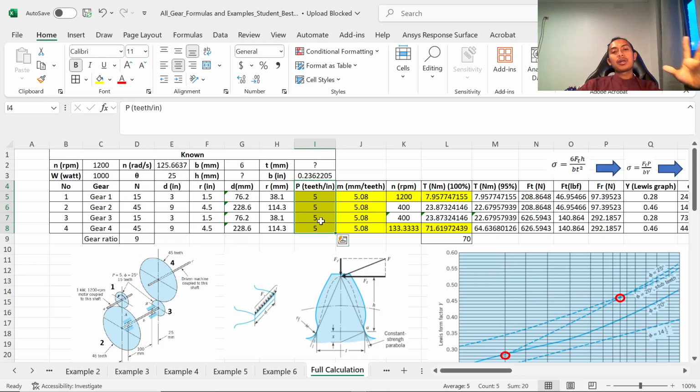Also the diametral pitch for imperial units and the module for SI units. These are the identity and compatibility values of your gearbox. This is normally standard: just put in some values and the software will generate your gear.